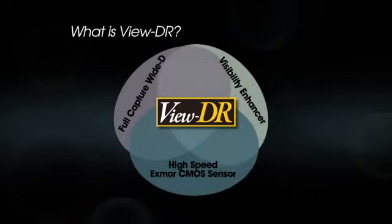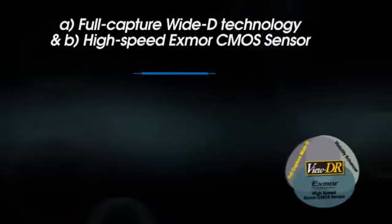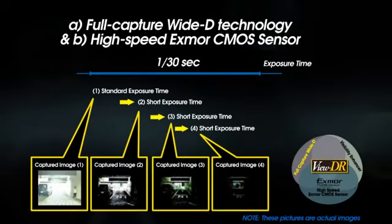ViewDR takes advantage of the unique abilities of Sony's new Exmor CMOS image sensor. ViewDR is a three-part process. The first part uses Sony's full capture YD technology. For our 720p ViewDR-enabled cameras, this entails capturing the image 4 times with 4 progressively faster shutter speeds within the 1/30th of a second acquisition time of the sensor. The low shutter speeds expose the dark parts of the image correctly. The higher speeds compensate for bright areas in the picture.